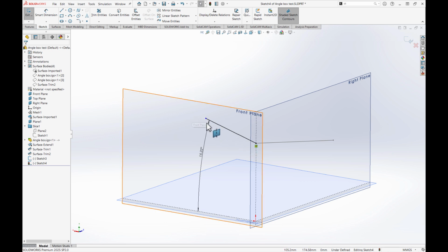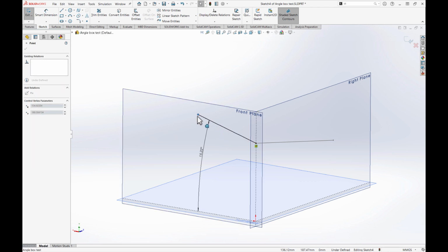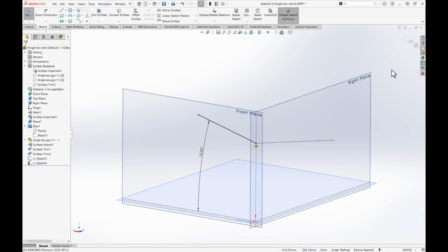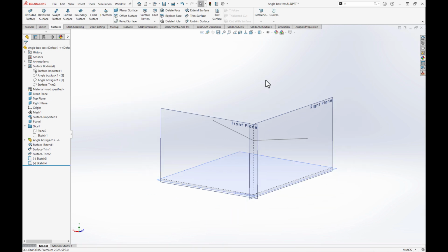And then I could put a length on here again, but I don't really need to. It's okay in terms of these sketches to leave that slight under definition just to do with the length of these lines. So that would be acceptable in these sketches. We've defined everything else that is important to us. So now I've got those two lines.